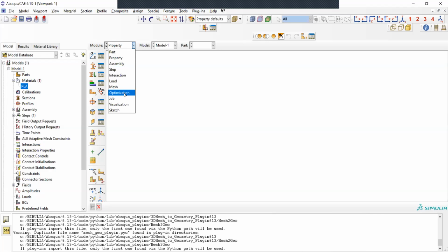One more step that you will not need now, and I assume it's not generally needed, is an optimization step, where you can, as your colleague showed us a while ago, he had a solid model and he used the software to remove material from that solid model. So this is something you can also do on Abaqus, to do a weight optimization, and the software will run a lot of simulation cycles, iterations, and reduce the mass, remove material with every cycle to optimize the weight of the part. So this is something you could have used for your design, and you can still use it for your design, but it is not part of our lab. It's something that you can experiment with on your own if you'd like to.